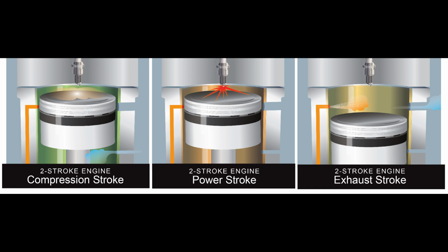Detonation is an uncontrolled, explosive ignition of the fuel/air mixture within the cylinder's combustion chamber. It causes excessive temperatures and pressures which, if not corrected, can quickly lead to failure of the piston, cylinder, or valves.